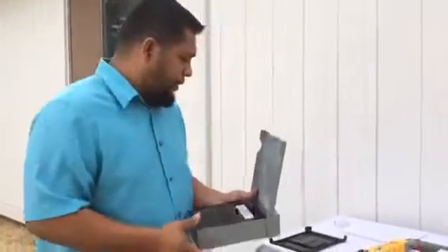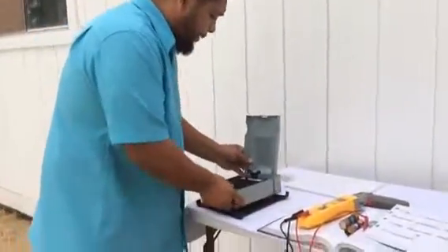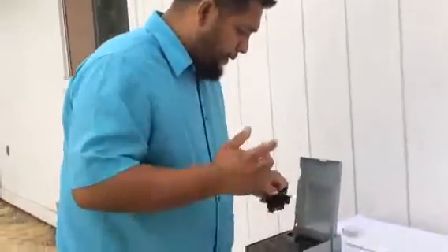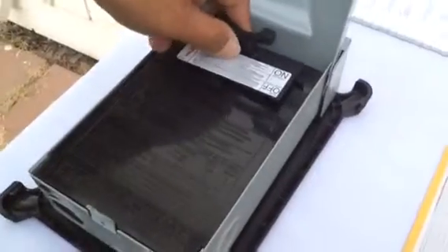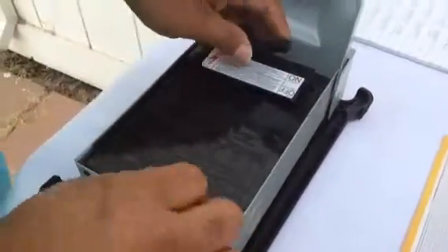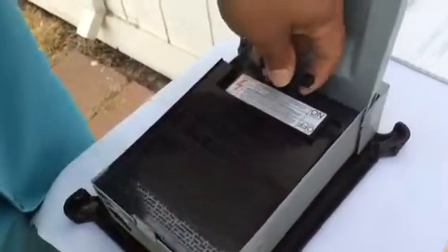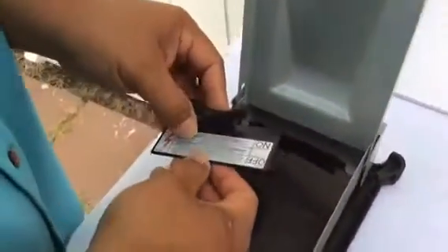Let me give you a closer look at what this disconnect box looks like. We have a disconnect pullout. In order to get into this or pull this cover off, you can see that the cover will not come off unless you pull the disconnect out. This disconnect allows current to flow through the box from the line voltage to the load side, and I'll show you that in just a minute.